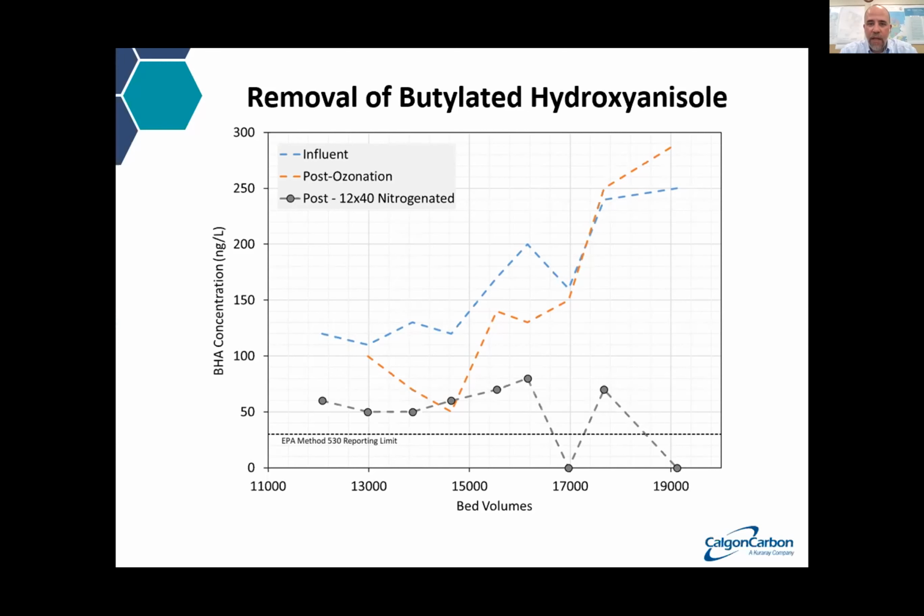So the positive takeaway here is that we don't see a lot of removal, at least steady removal through the ozonation system, because this is an antioxidant, so it would be resistant to degradation. But we do see, most likely through biological methods, just not straight adsorption, removal through the activated carbon system to a fairly decent degree and to some extent below the reporting limit there of about 30 parts per trillion.